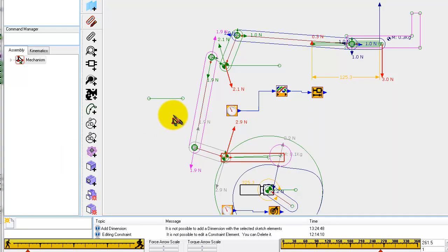So we need to add a spring to keep the roller in contact with the cam all the way round, otherwise it will be tapping out a very mischievous rhythm. We could cheat with a groove cam, but no, that would make the cam too big, which wouldn't fit into the box. Let's add a spring between the ground point here and the end of the follower rocker here.